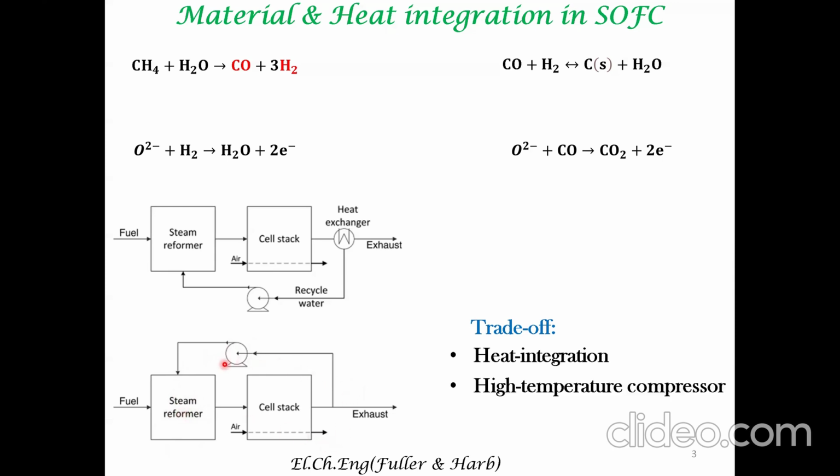However, when we try to do this instead of the other approach, the compressor that is being utilized has to be a high temperature compressor, which can be more expensive than the simple compressor. In addition, when you recycle the entire exhaust, it also decreases the concentration of H2 and carbon monoxide in the reformer.